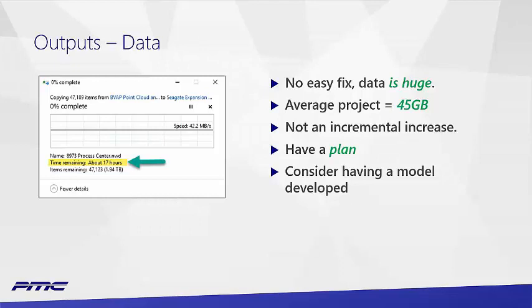A concern with outputs, as you manage a project that involves point cloud data: even very well organized point cloud data sets that have been filtered and had everything done right to them are still very, very large. It's important to understand they're larger than probably any other data your company has ever seen. So if you have not worked with point clouds before, you need to take some steps to prepare for point clouds coming into your office environment. You likely don't have enough capacity on your file servers to hold the data. There are different workflows you need to get right to keep your project moving forward.